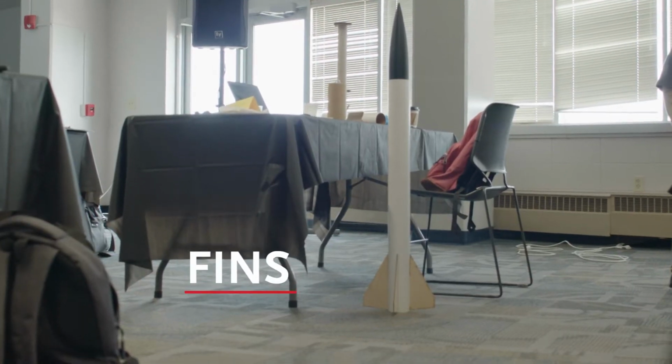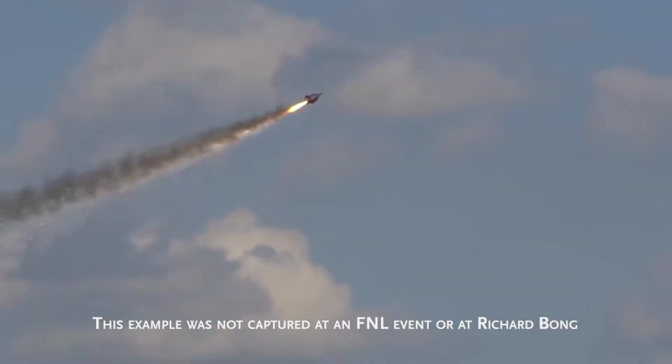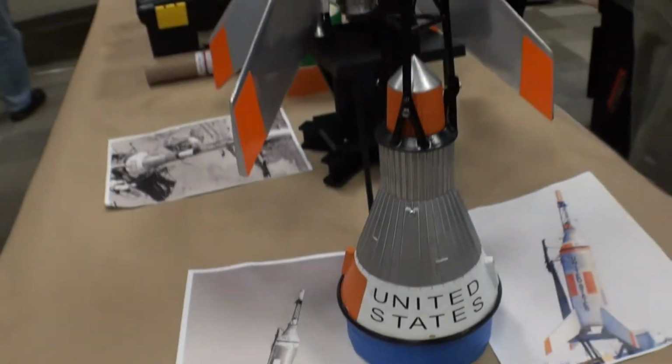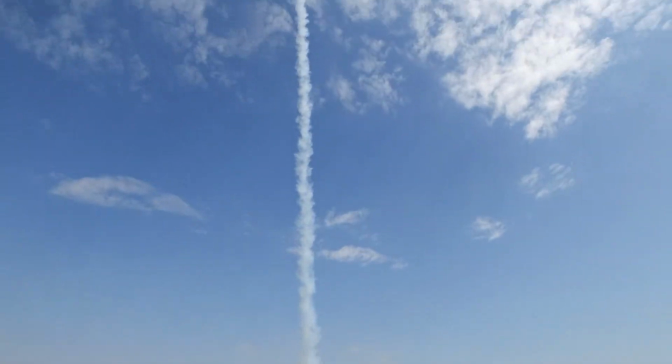The fins provide the rocket stability and control. Changes in the air can make the rocket turn. If it turns too much, it can go off course. The effectiveness of fins depends on their size, shape, and surface. If the rocket attempts to turn, the air pushes more on the exposed fin surfaces until the rocket rights itself.